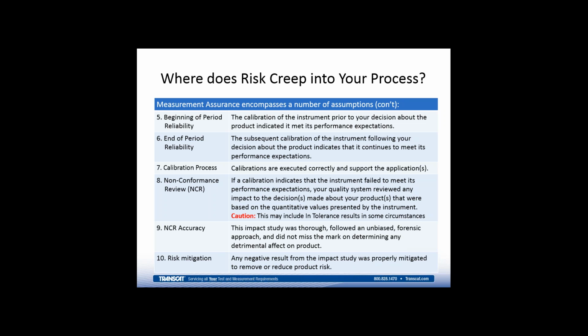The calibration process itself, if the calibrations aren't being performed correctly, or if they're using the wrong specs, wrong methodology, there could be a number of reasons why you think you have a good calibration result, and when you dig into it, maybe it wasn't done correctly. It does happen, more than it should, so buyer beware when you're sending out instruments for calibration to any external supplier and even for internal labs.